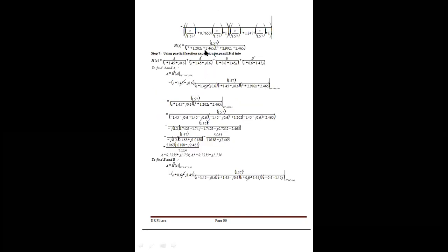Since we are designing a low pass filter, we will be finding H(s) by replacing s with s by 1.57. So replace over that, what we will be getting is 1 by (s by 1.57 the whole squared plus 0.76537 s plus 1) into (s squared plus 1.8477 s plus 1). Okay, then you take a cross multiplication and simplify the expression. So we will be getting 1.57 to the power of 4 divided by